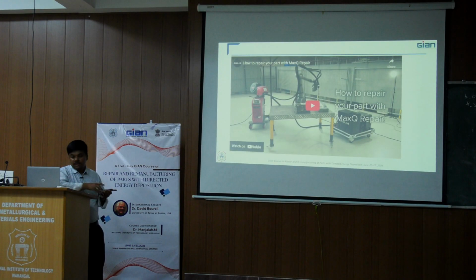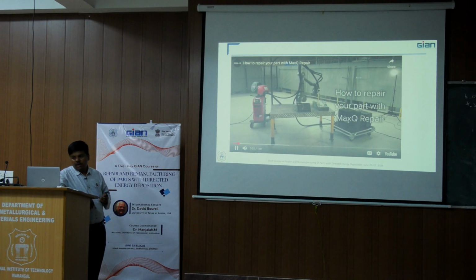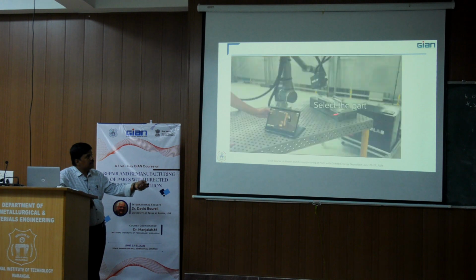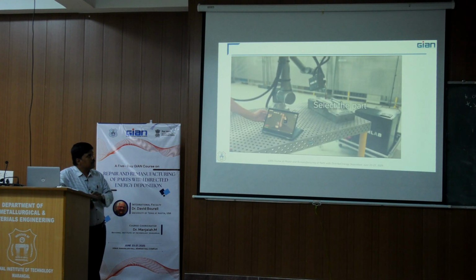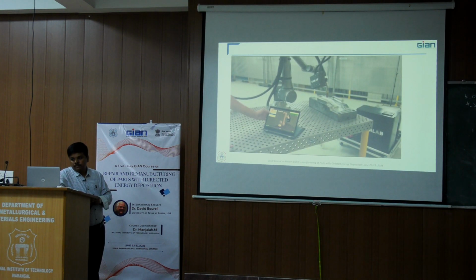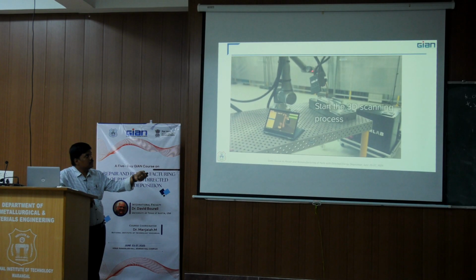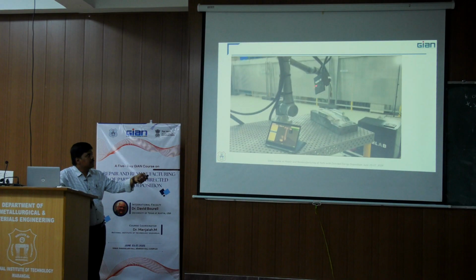And if you see, this is another component. They have made the scanning along with the depositions and all. If you see here, the scanning data will work, as well as the repairing data, in the same robotic arm of your laser DED process also. This is the 3D scanner they have attached to your robotic welding, with the laser DED process.